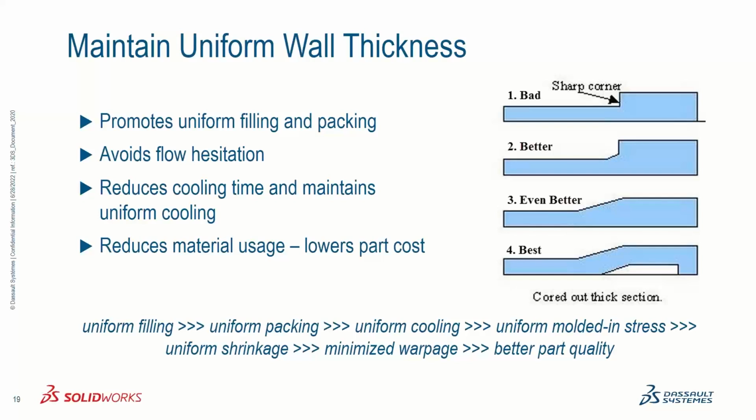So a little bit of a better design would be to put a chamfer in the region where you're transitioning from thin to thick. And probably a slightly better design would be to have a more gradual transition from the thin to thick region.